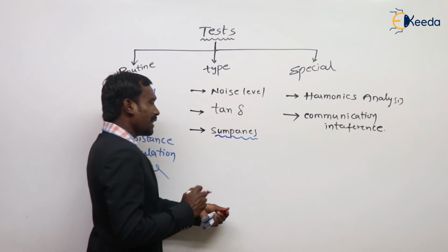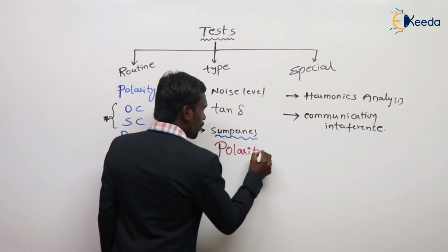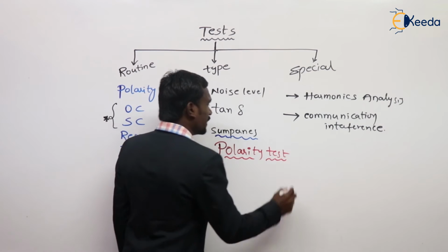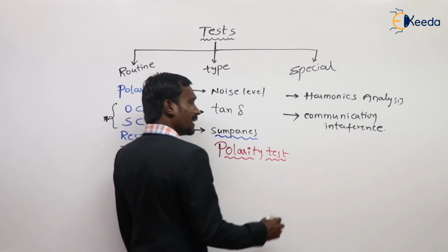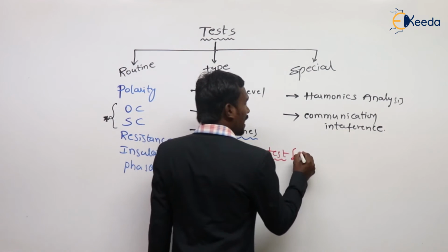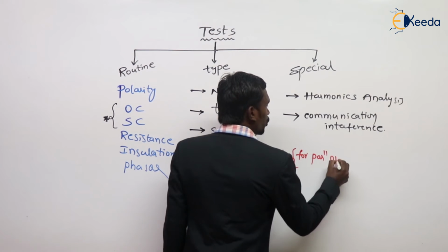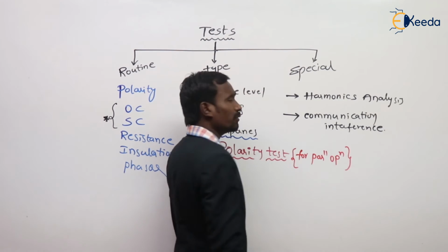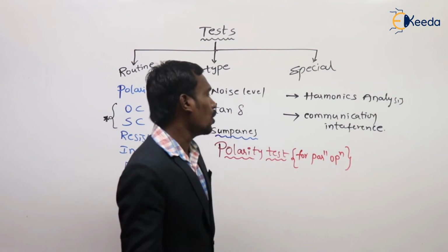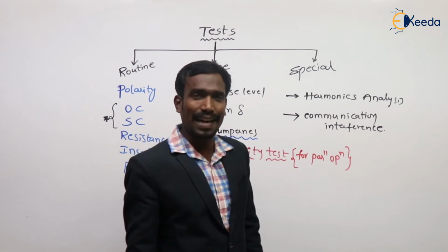Let's see here, the polarity test. Sir, why should we do this polarity test? This polarity test is very important. We should know the polarities for parallel operation. Otherwise, it may lead to short circuits. To know the polarity, we should do a test called the polarity test.